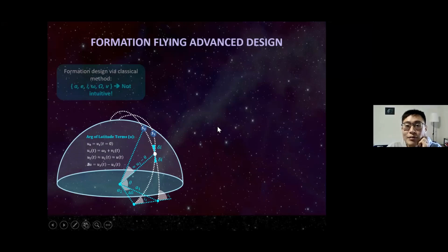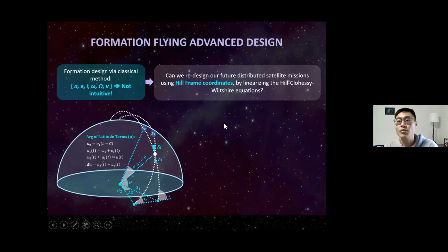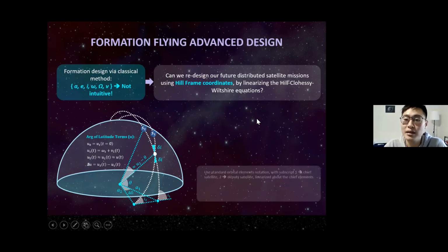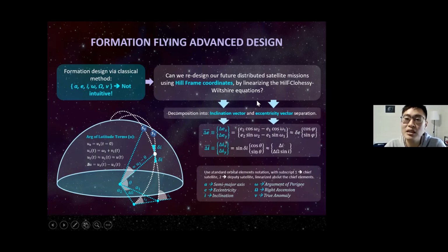But basically, this is just to introduce the formation flying orbit paradigm. So you notice these six elements. These six elements are the same elements that we discussed at the start of the class: semi-major axis, eccentricity, inclination, argument of periapsis, and right ascension of the ascending node, right? And again, we pick the initial elements. We call this a decomposition into the first order Clohessy-Wiltshire equations. And we can actually describe relative orbits using relative eccentricity and inclination vectors.